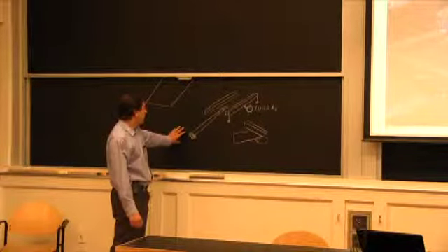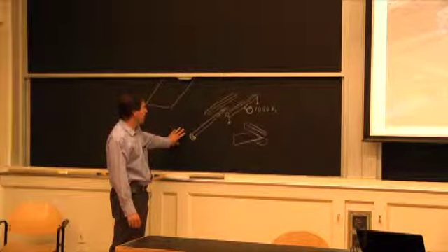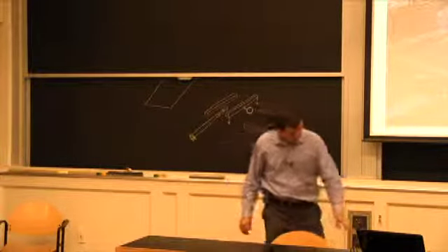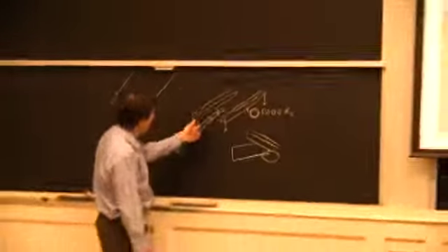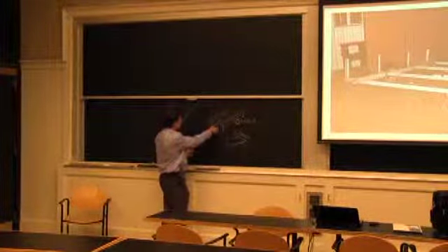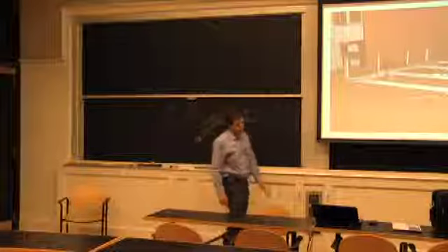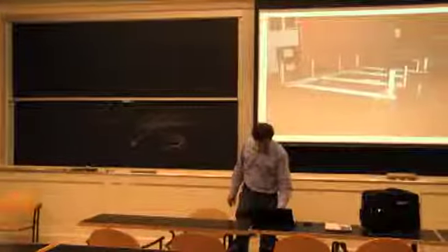The idea that, for example, if we look at it, this is the frame, so you can see over here in the middle that the main member here is going under, because when I load this up, it wants to push, and this one wants to go up. So that's why I want to have the cross member on top here. That's really where the load is the highest, at the front cross here.